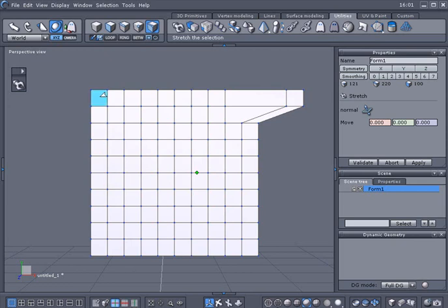Alright, now this time, instead of just clicking and letting off my mouse, I'm just going to hold the left mouse button down. Before I do it, keep an eye down here because I'm going to be tapping the space bar, and I'll let you know when I do it. So I'll just click and drag this time. Alright, now I'm getting ready to tap the space bar, so keep an eye on the bottom. As you can see, the ruler constraint went to that direction. And as soon as I let go of the mouse button, it automatically jumps back into no constraint, which is very handy.